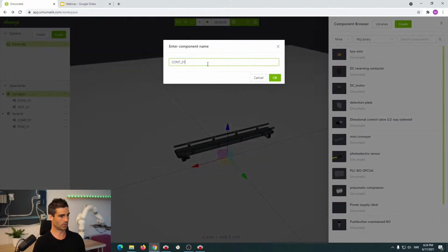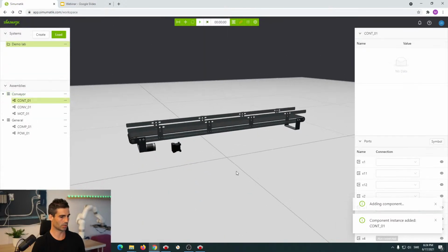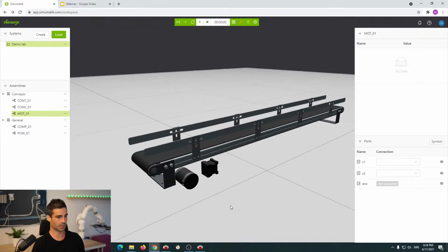We call it cont 01. So now we have the motor contactor. Let's put everything nicely in its place. We can move with these arrows, and then we can also rotate the elements. We select the rotation tool. We can always position all the elements manually with the arrows, or just type in a number here in the helper. So now I'm gonna rotate it just exactly 90 degrees.